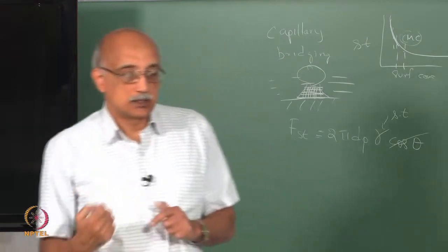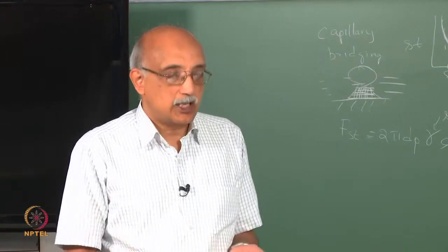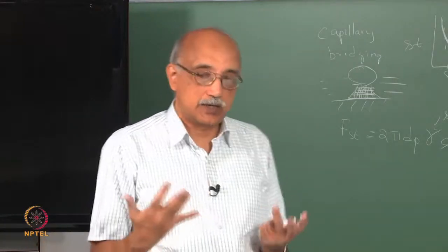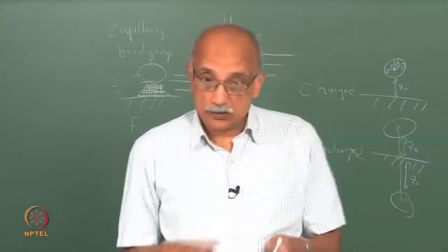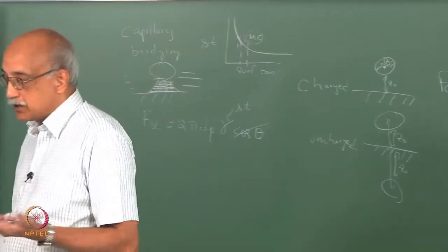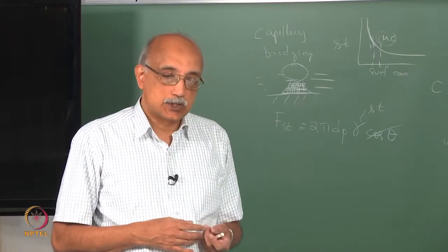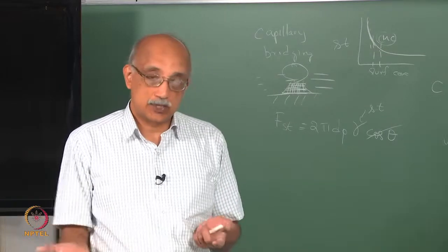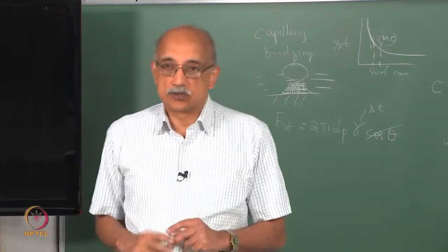So, the point is that if you have a surface that you are trying to keep clean, it is a good idea to keep it wet, because although surface tension based forces can increase, all the other forces decrease. As we have seen before, electrostatic forces will drop because static charges dissipate in water. The van der Waals forces will drop quickly. So, in general, keeping a surface wet is the right thing to do, but then you have to make sure that all the particles on the surface are removed before you allow the surface to dry.